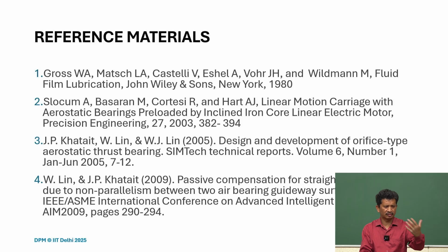One can start gently and develop a system, maybe one axis, then go for two-axis systems, and then embed the third axis. Many of these diamond turning machines, and even machine tools, need that, not only for production or inspection, but even high-end measurement systems, SEM, and even these CMM machines.